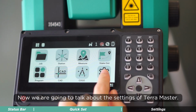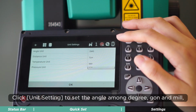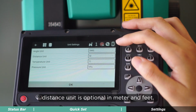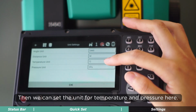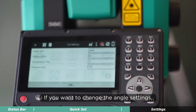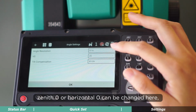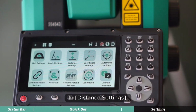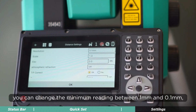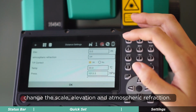Now we are going to talk about the settings of Terra Master. Click Unit Settings to set the angle among degrees, gon, and mil. Distance unit is optional in meters and feet. Then we can set the unit for temperature and pressure here. If you want to change the angle settings, zenith 0 or horizontal 0 can be changed here, and the tilt compensation. In distance settings, you can change the minimum readings between 1 mm and 0.1 mm, changing the scale, elevation, and atmospheric refraction.